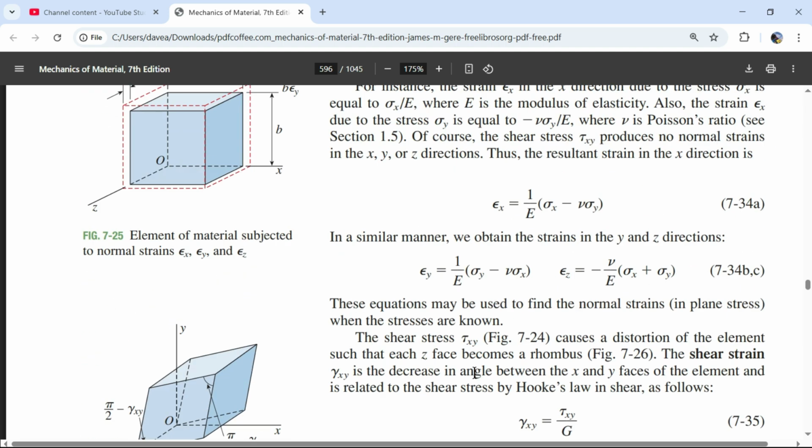And so let's go back up to these equations. Let's say if I solved this equation for sigma x, I could throw it into right here. And then I would have an equation relating sigma y and the strain in the y direction. And if I solve this for sigma x, it would also have strain in the x direction. So when I shove it in here, I could get my sigma y terms together, and then I would have an equation for the normal compressive or tensile stress in the y direction as a function of the strains. So yeah, algebraically I could do that.